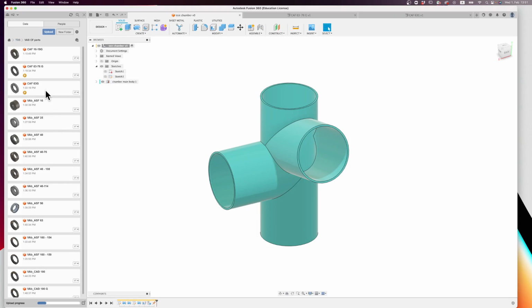Oh yeah, it's a lot more loading right now. And so this is a weld flange that is tapped. So the G stands for Gewinde in German, tapped. Always make sure that you get the right parts, because otherwise you're going to get chambers that either have taps where they're not supposed to have taps, or the other way around, or they might be movable if they're not supposed to be movable. Anyway, so you can insert that into the current design.